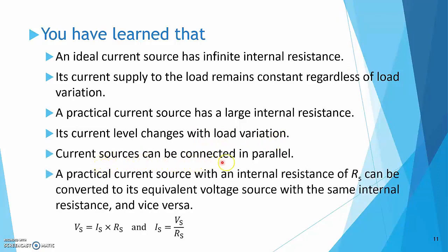Current sources can be connected in parallel. A practical current source can be converted to its equivalent voltage source and vice versa. A pair of equivalent sources have the same internal resistance. Voltage source, current source, and internal resistance obey Ohm's law.